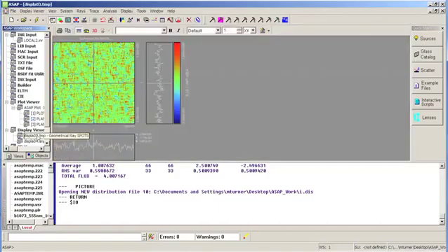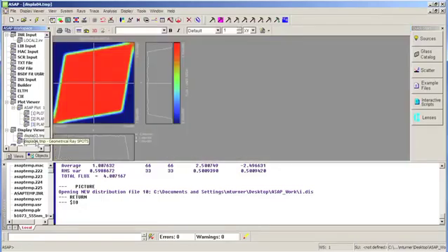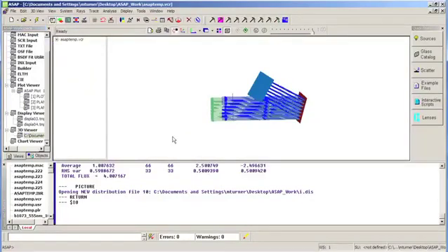And similarly, the false color plot shows the same type of data. However, if we look at plane 3, which was the skewed surface, what we see is a ray distribution that looks like this. And in the false color plot, we see the same information. Now, as you saw previously in the figure, this surface is square, and our light distribution is square. So we would typically expect a square spot pattern or radiance pattern on that surface.